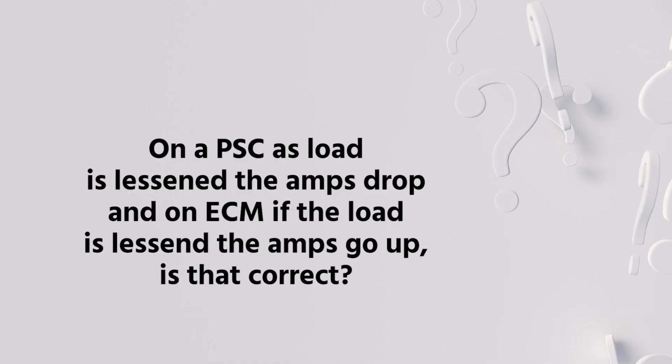The total static is taking my inlet side, which is a negative static pressure, changing the sign of that, and adding it to the positive static pressure on the outlet side. That would be the total static. That's a good question. Thanks for bringing that up.